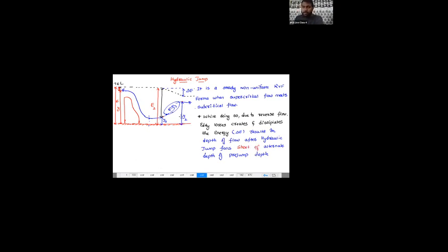See, you see this figure, my dear. If you see this figure, first of all, you look over this portion, E and E1. You know E is equal to E1, which means y and y1 are alternate depths.